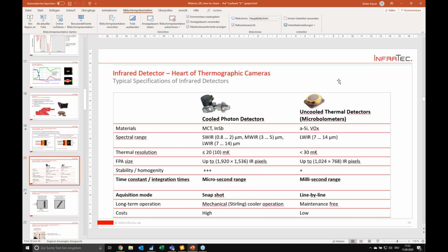These 0.5 and 0.3 clearly come from related body temperature measurements these days, and they are only suitable for a limited temperature range and limited ranges for environmental or camera temperatures. To describe the whole calibration process of such a camera is a little bit more complex, but you have to understand the whole calibration process to really understand this.